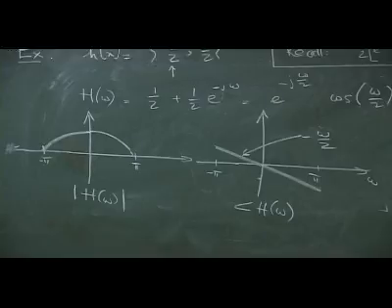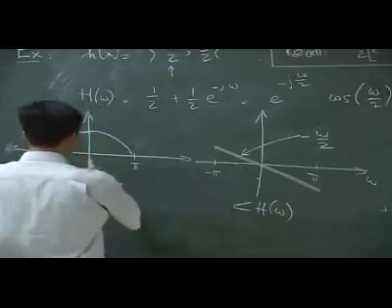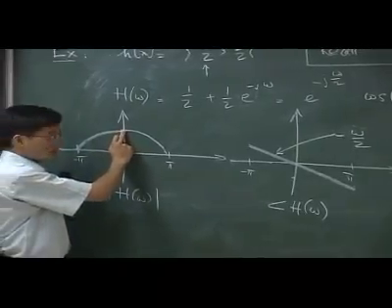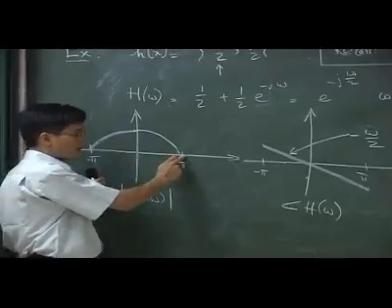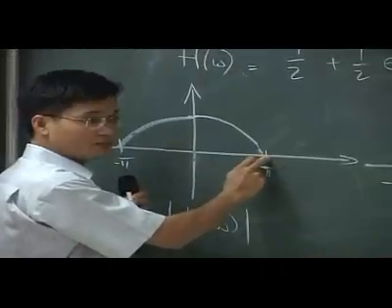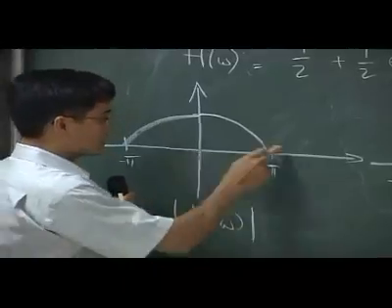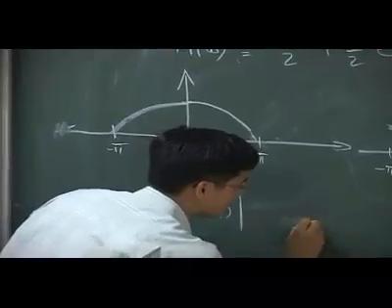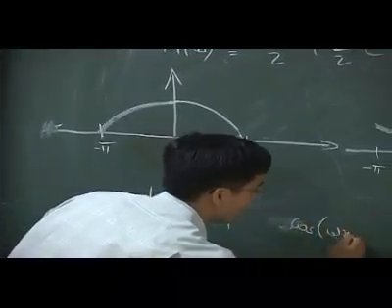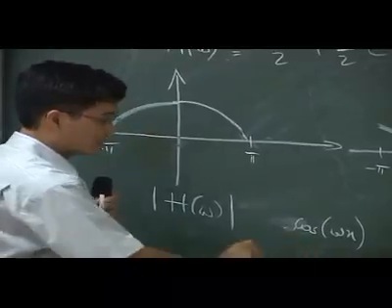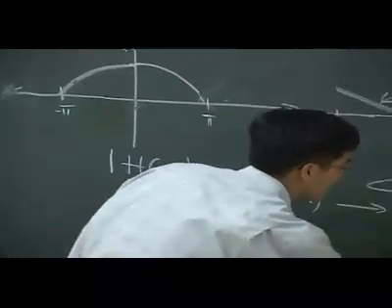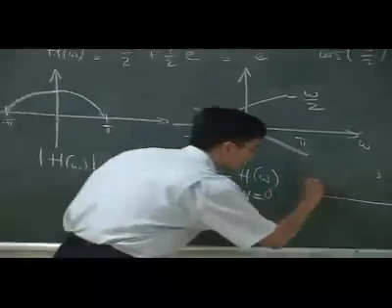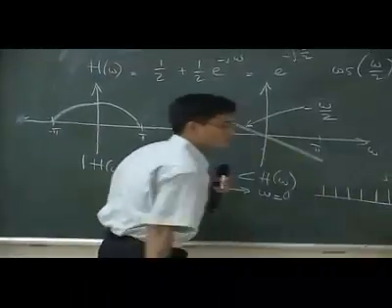Now what is this filter doing? Well, you see the signal when omega equal to 0, it can go through. And then slowly decays. So at omega equal to pi, it rejected. Right? So let's see what the signal between these two is. So look at this signal, cos of omega n, this basic signal. Well, when omega equal to 0, what I have is just cos of 0, so it's just a constant signal. Boom, boom, boom, right?